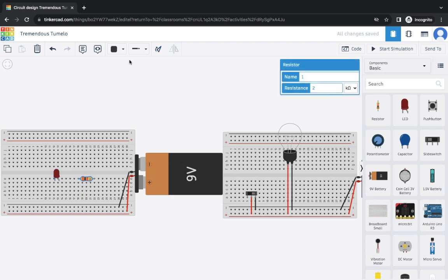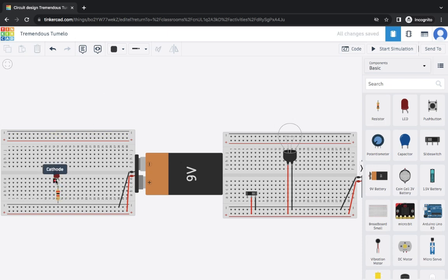Something curious about the resistor is that we can use the resistor on the positive or negative LED pin. It doesn't matter. The resistor doesn't have any restricted position, okay? So I'm gonna use cathode. Remember what I said, cathode is negative. So we take the wire from cathode to the negative row. And then I'm gonna use the red color for my positive, that is called anode. Terminal 1 of the resistor, click. Terminal 2 and go straight away to the positive power rail.